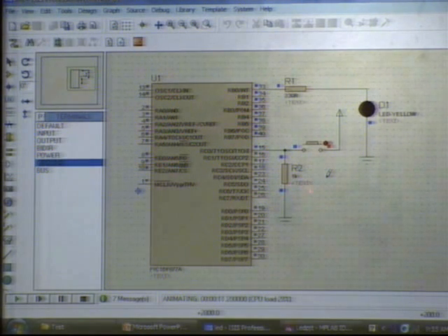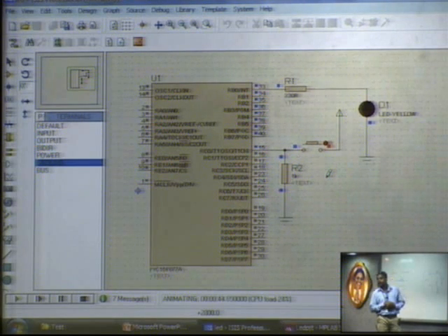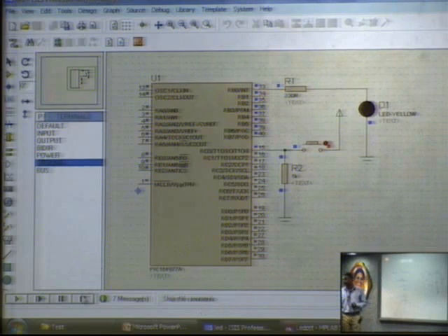So here you can see when it is running, the switch is open, no? When the switch is open, due to this pull down resistor, you can see all these are zeros. But in the Proteus, if you are omitting this resistor also, it will work. In this Proteus, there is some problem for the simulation. All simulation may not be correct. You try removing this, then also it will work sometimes. But when you are doing actual hardware, this resistor should be there, otherwise you will not get the output.